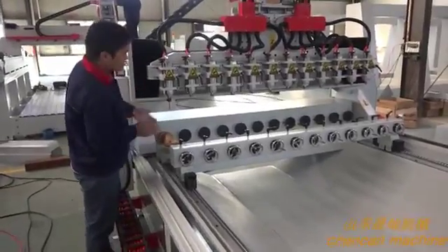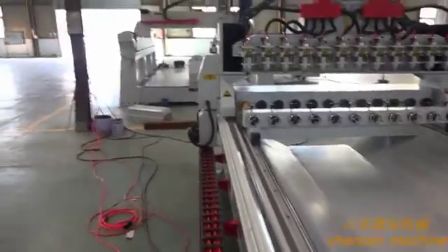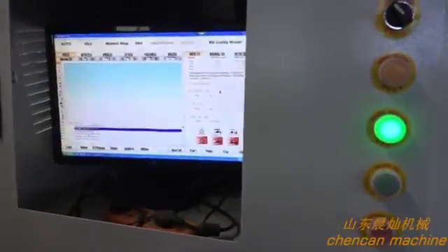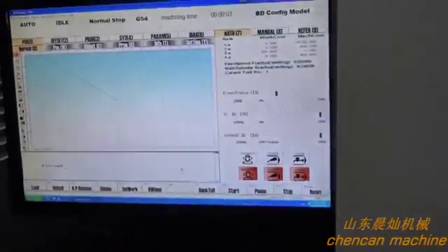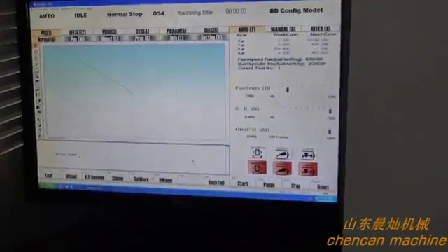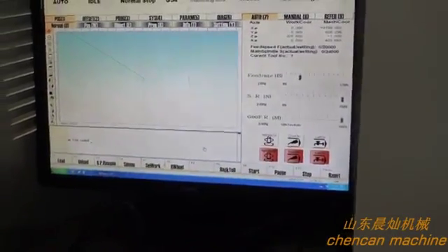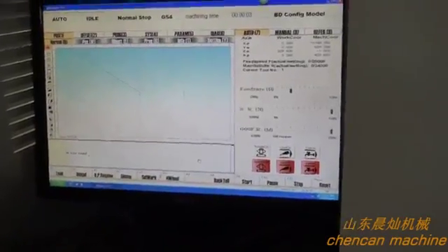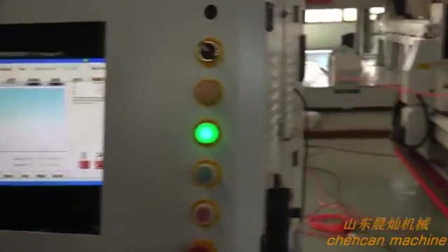Use the spindle to tighten. These files are no longer needed, so we unload them. And the Z we should reset again, because we changed the tool, so the Z place has changed. Now the X and Y and the rotary are no problem. So now we go to change the Z with the hand wheel.